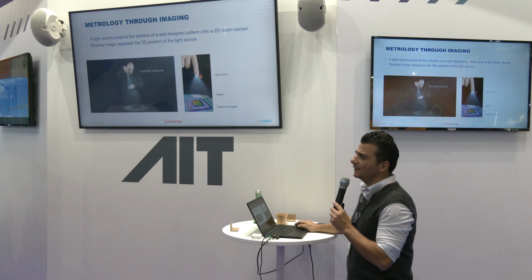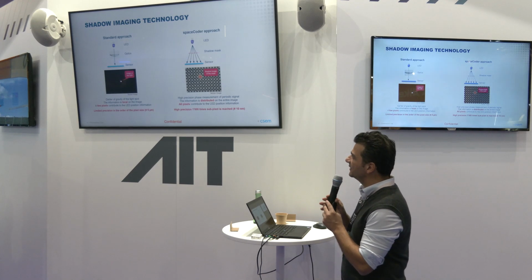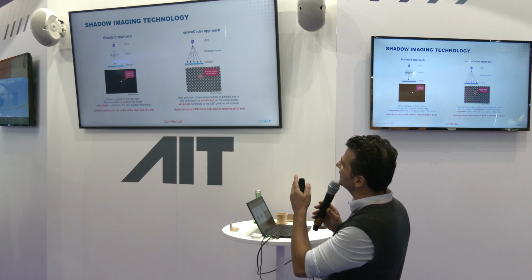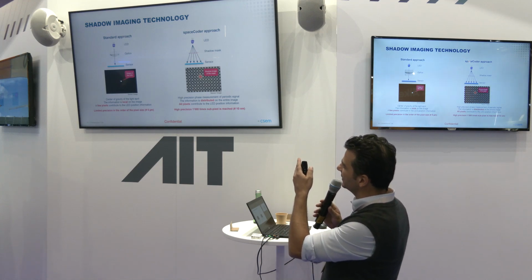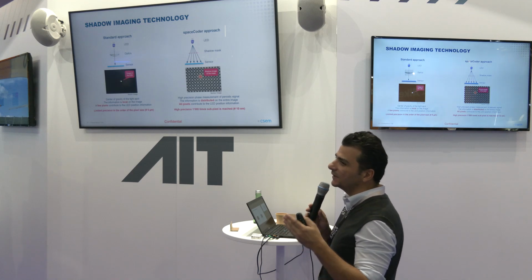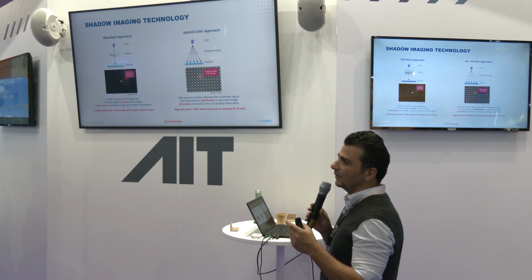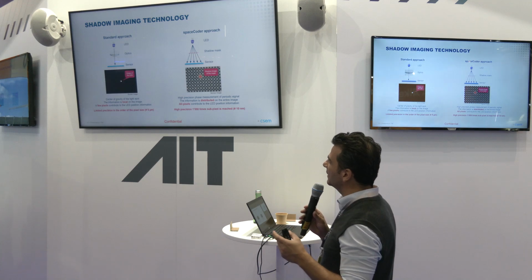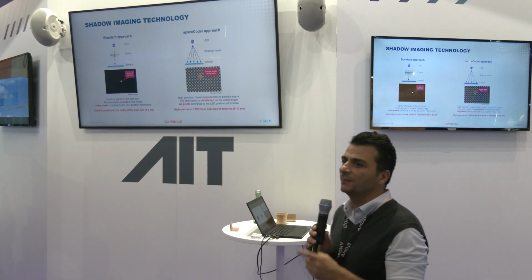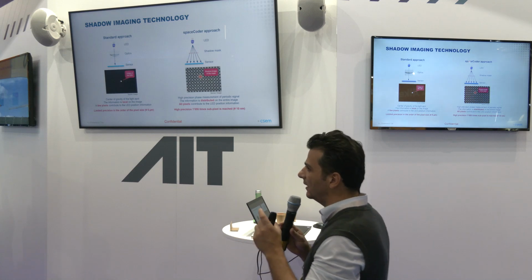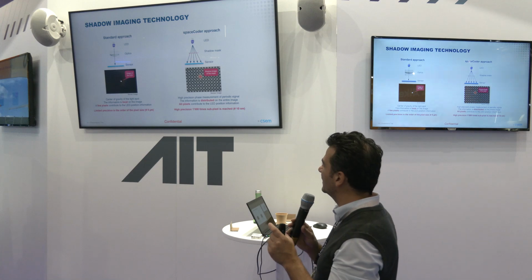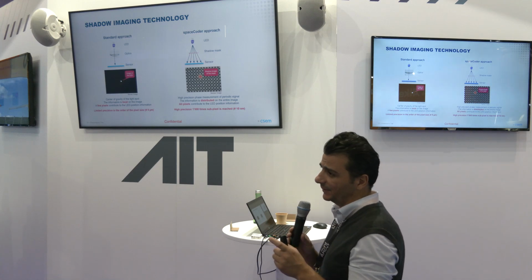To give you an idea of the added value of this type of metrology system, if you compare it to a standard approach where you have a single LED, an optics and a sensor, the spot size that you end up with on the detector is a few pixels wide. The resolution is on the order of magnitude of the pixel pitch. We could interpolate, but we end up with something in that range. On a typical imager, I have a pixel pitch of 5 microns, so we end up with a precision limitation of 5 microns.